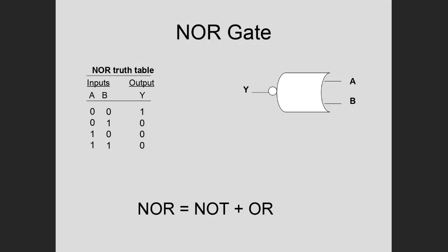So if you remember for the OR gate, the output was, I had a 0 and every other one was a 1. Well, here if I invert that, I get a 1 and every other one is a 0. So why do we have these opposite gates? Well, you'll see they actually make life a lot easier by having AND logic and then the opposite logic.